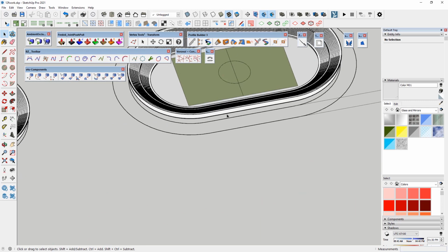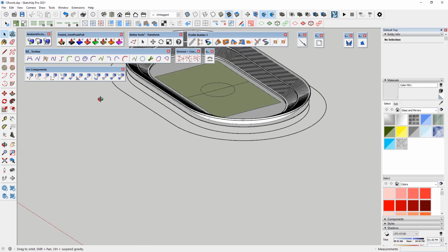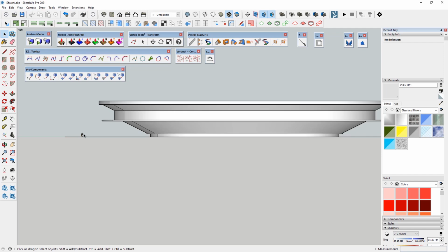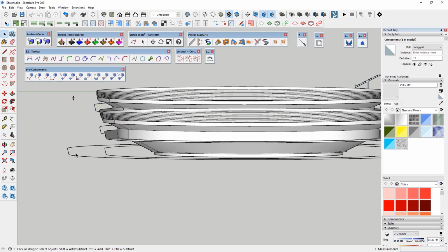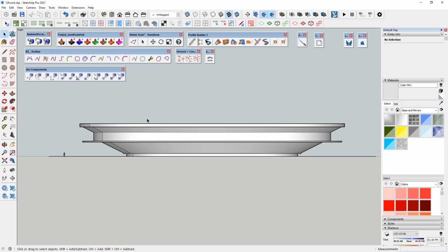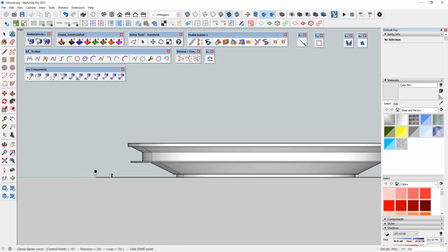Okay, and now I will just remove this offset. First we need to create some reference lines, so it means reference shapes for our construction, for our glass that will be built in the next steps. To do this, I will use the Bezier toolbar, for creating some main shape for the section. We can use the classic Bezier curve, or for example uniform B-spline. It depends what you prefer.